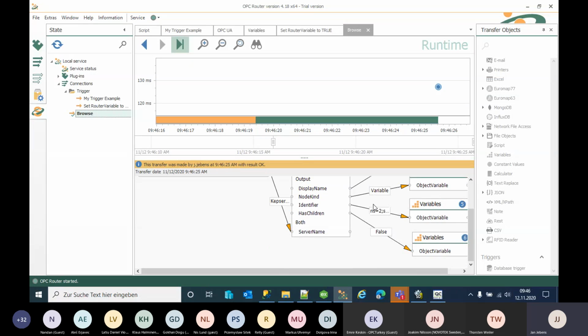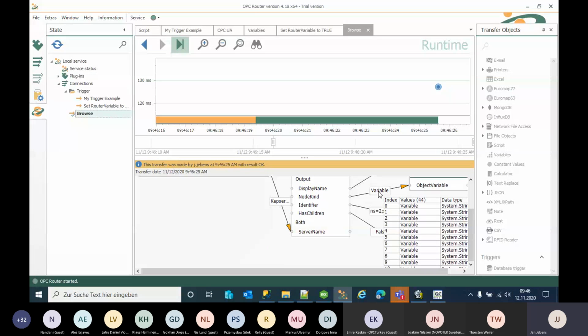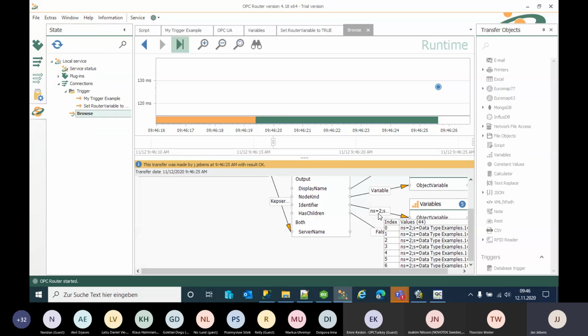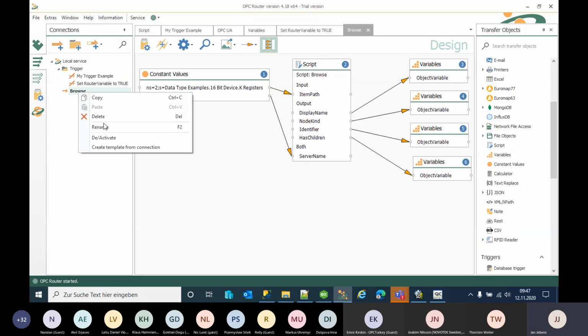So you know the data type, you know what object type in after OPC UA specification it is. You have the namespace, the path to it, and the values to it. So the browse functionality gives you a lot of good possibility for dynamic actions. So that's why I showed it. Please remember the reference to system core and the using namespace of link. Otherwise, it's copy paste.